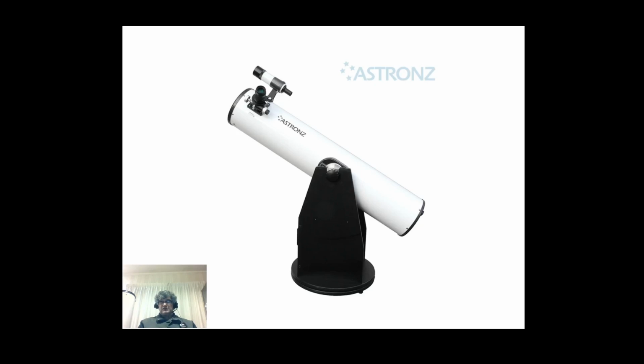And the idea is you adjust that so there's a bit of resistance to the mount being turned, but it offers enough resistance so that it just won't be easily knocked off target. And similarly, the other bearing, which you can see if I bring the mouse pointer in, this bearing here sits in a recess in the rocker box, and there'll be a lining there, I think usually of formica or something with a really smooth surface for it to move on.